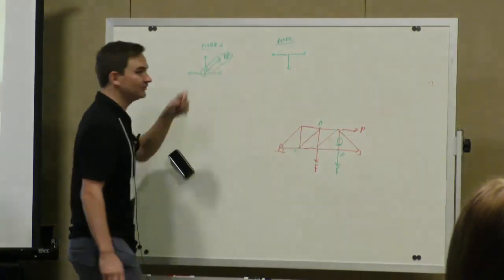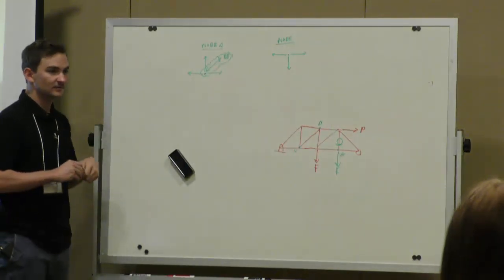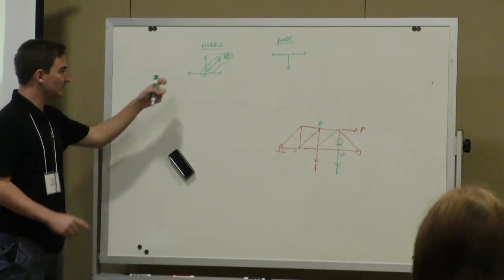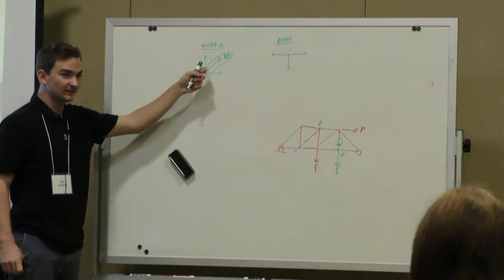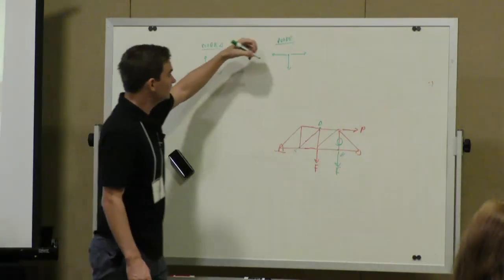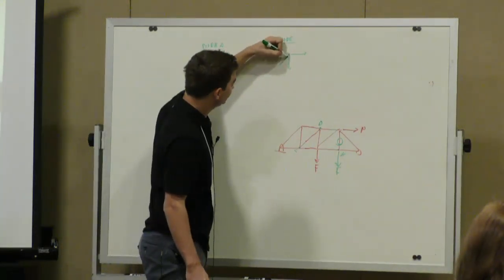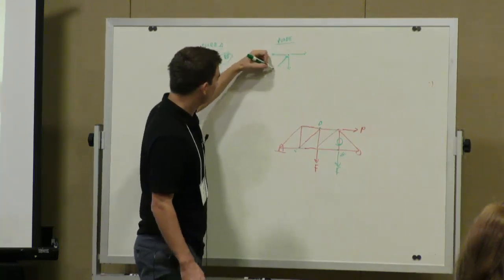So this is in tension, this is in tension, and this is tension. Which direction should you draw AD? You should draw it up into it. Yeah, since it's under compression, determined at node A, you would draw it into the joint. So therefore, this is AD.